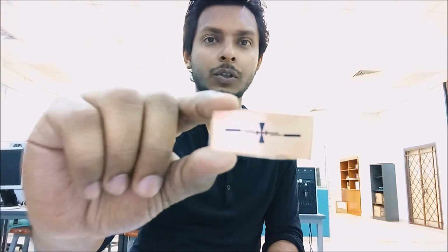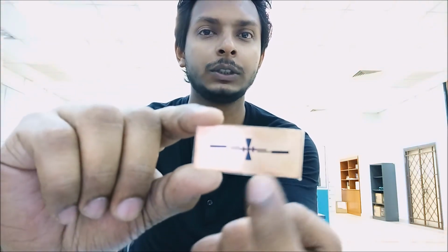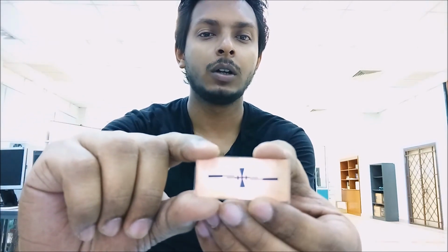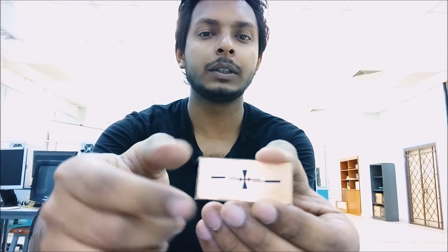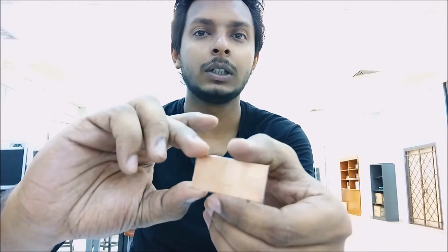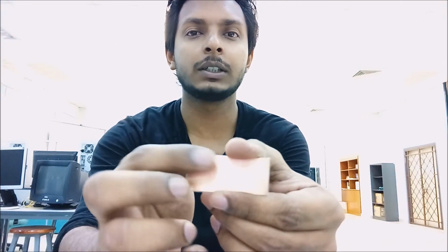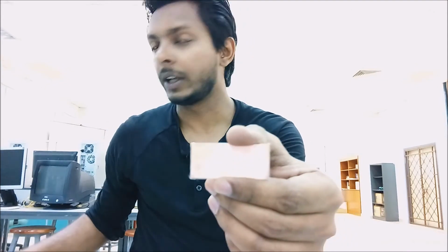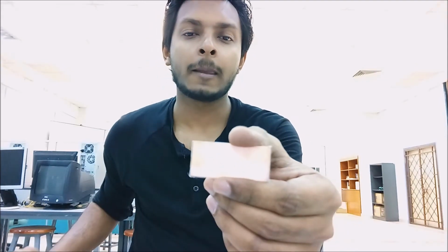Alright, we're done with the pasting process. We have printed and pasted like this. As you can see, the black portion is our design. We have pasted it, and we removed the printed paper and the heat protecting tape, and uncovered this and covered the other surface, the ground plane, protecting the ground plane with the regular duct tape by using this.